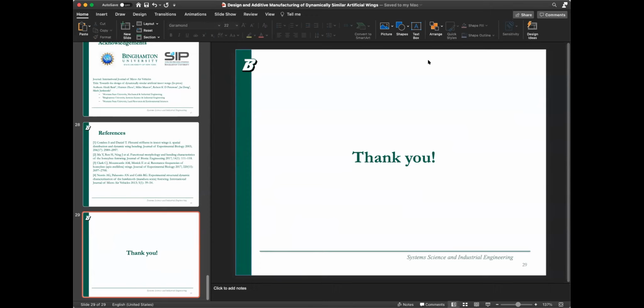Yeah, thank you. Okay. So, sir, if I can pitch in here, SMA would be overkill in this particular application, because it has a lot of strain energy density that it can provide, which is not really required for a micro aerial vehicle. Another thing is the frequency response. Since SMAs are thermal actuators, cooling them is a problem, and when you have to operate this MAV at very high frequencies, that becomes a challenge. Okay, I understand. Okay, fine.